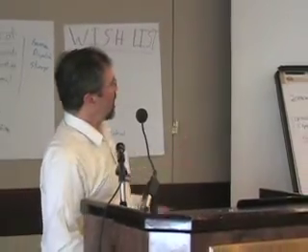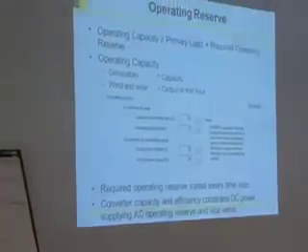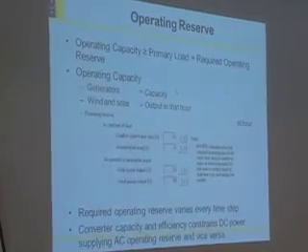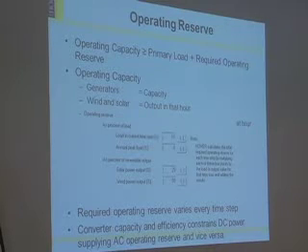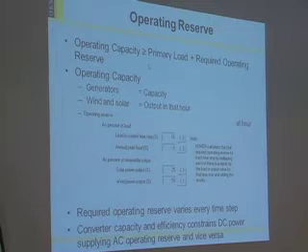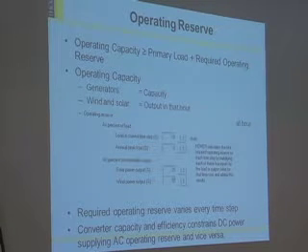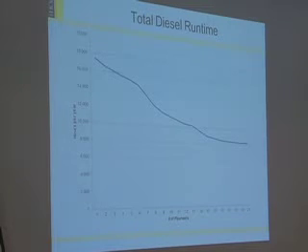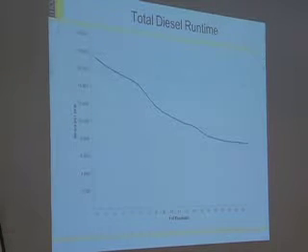Actually, this is a pretty simple formula, although I'll admit, I have to keep reminding myself of it. But if you just go back to this formula, you can understand how Homer handles operating reserve. And it doesn't say anything about the minimum load here, but it's just that the minimum load affects the results, basically. Now, I'm really afraid I've confused everybody. But let me go to a particular example,